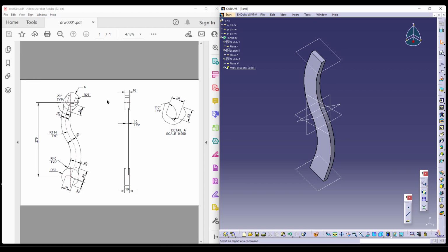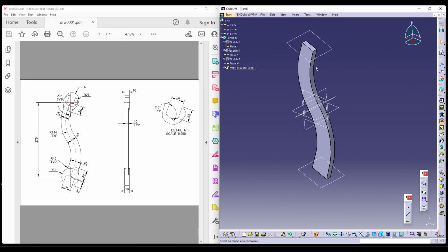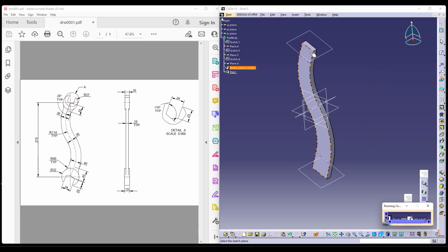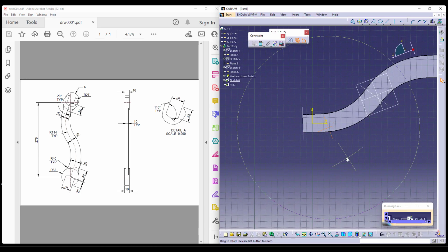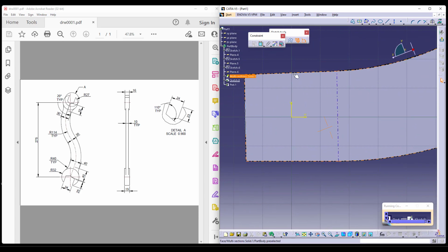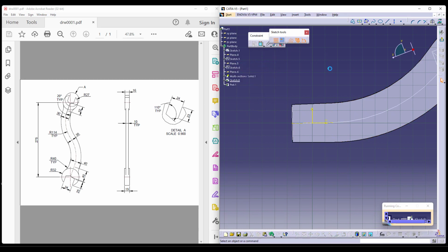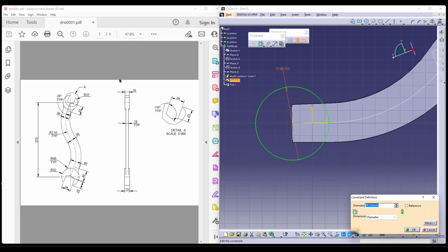To achieve these shapes, first let us try to remove a certain amount of material, or you can add material inside a material also. But in this software, it usually tends to merge the bodies, but all softwares do not do that. So, assuming the earlier sketch, let me try to unhide the earlier sketch. This is the reference which I will be using, and I will be making the circle over here. And the diameter of this circle, or the radii of this circle, is given as 27. So, I am just taking this as 27.